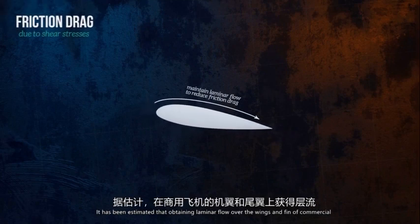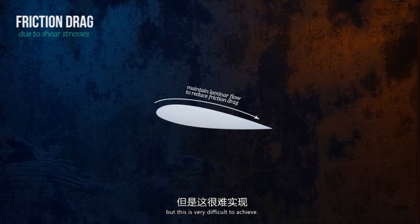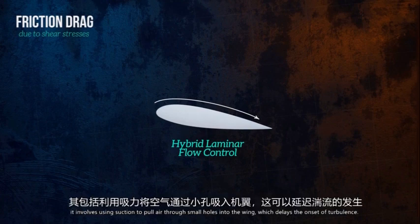It has been estimated that obtaining laminar flow over the wings and fin of commercial aircraft could reduce the total drag force by around 10 to 15%, but this is very difficult to achieve. Techniques like hybrid laminar flow control have had some success. It involves using suction to pull air through small holes into the wing, which delays the onset of turbulence.